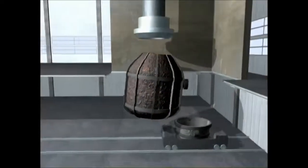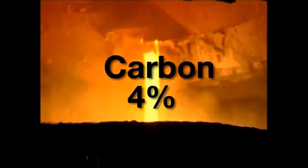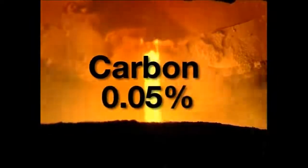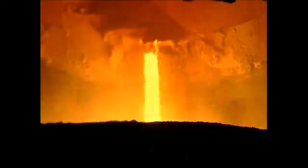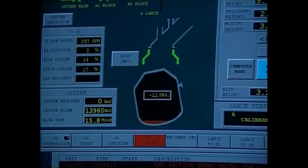During tapping, alloy additions are also made to adjust steel composition. By this stage, the carbon has been reduced from around 4% to about 0.05%. Finally, the vessel is tipped to remove the slag for recycling.